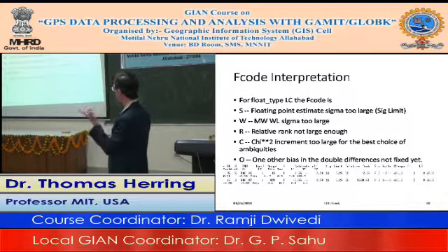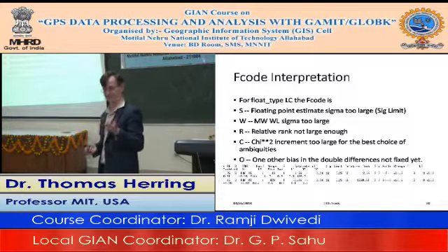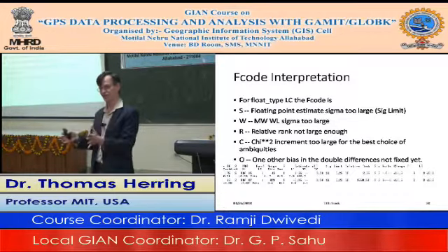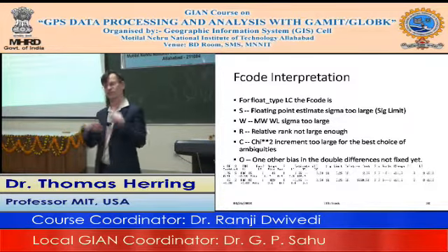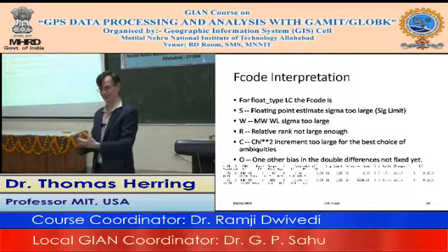But the thing that track does is it actually has a correlated noise model inside it. We've seen already, we see correlated noise everywhere. And when you have high rate kinematic data at 1 hertz, if you're assuming white noise, your uncertainties drop dramatically fast, and we know that's not valid. So it has a built-in correlation constant in it, and that is, again, meant to be conservative.